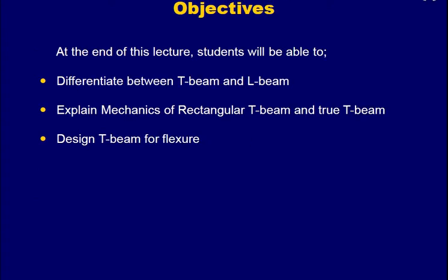The objectives are that at the end of this lecture, students will be able to differentiate between T beam and L beam and their difference with the rectangular beam, explain the mechanics of rectangular T beam and true T beam, and design a T beam for flexure.